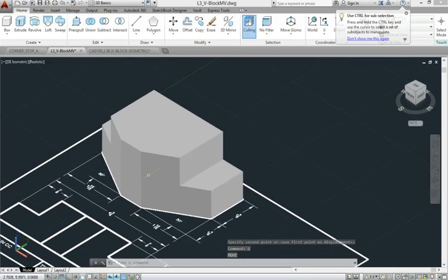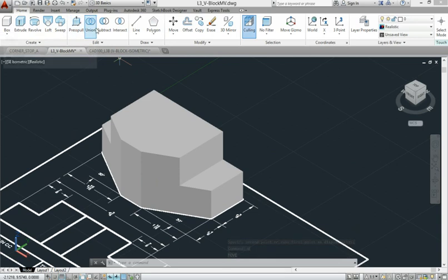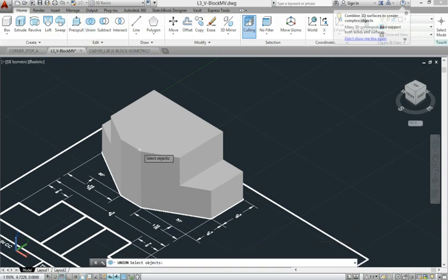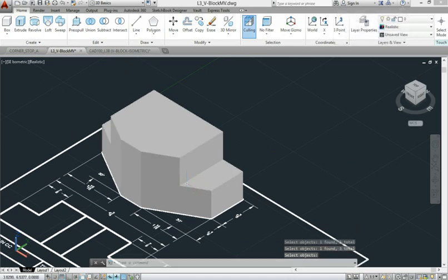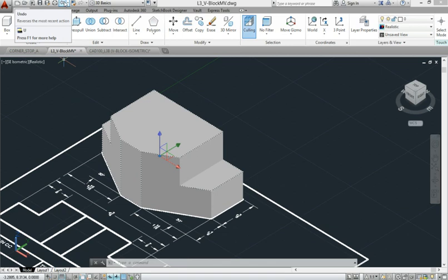In order to make this one solid object, the command is called union. Pick union, select your 3 features, click enter, and it unions the pieces together. Once a union is created, that's the final step of a 3-dimensional object. You can't reverse that process unless you use the undo command to return back to its original state.